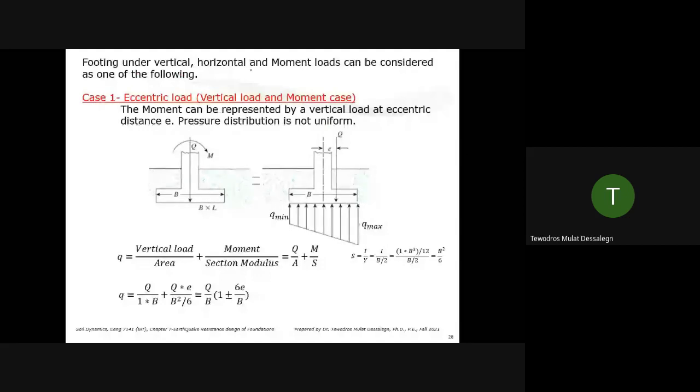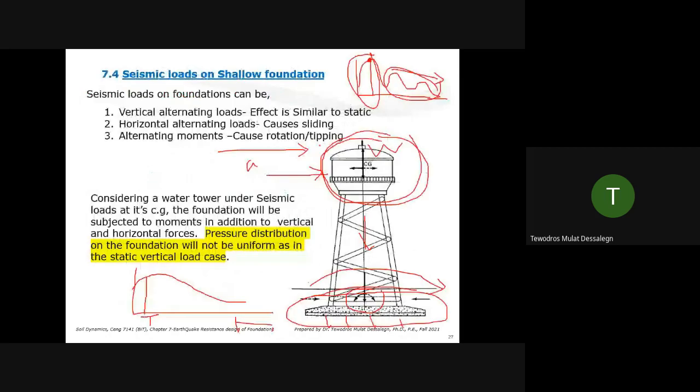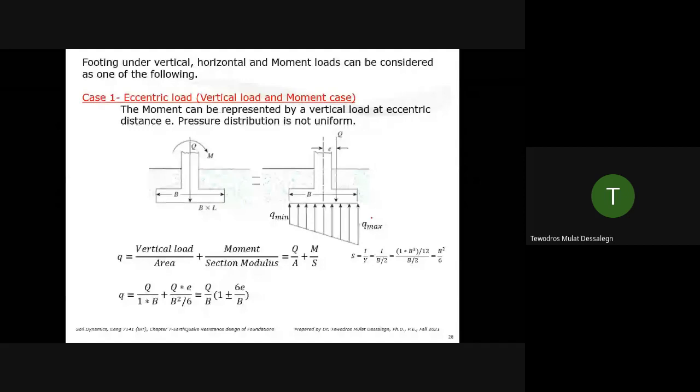So footing under vertical, horizontal, and moment loads can be considered as one of the following. Now, if you convert, let's say, the previous slide using response spectrum, you pick your acceleration. Now you found your axial force, lateral force, and moment. I'm sure you studied eccentric loading in your undergrad foundation class or in advanced foundation class. You consider eccentric loading, right? That's very similar to seismic.